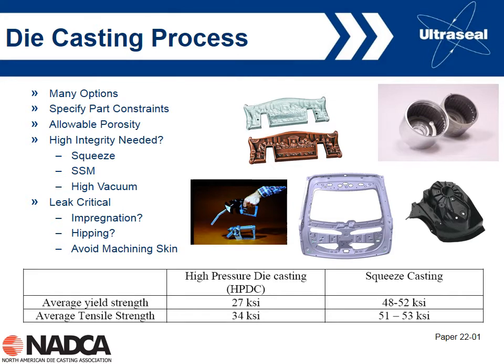Another thing, with all these different die casting processes, we're also going to get different mechanical properties. But basically the point of showing all these castings is that we need to design the die for the appropriate process. With conventional die casting, we obviously use conventional gating. With high vacuum die casting, we use a different type of gating, generally a much higher number of gates. With squeeze casting, you normally use a single gate, but a much thicker gate than you would with die casting.